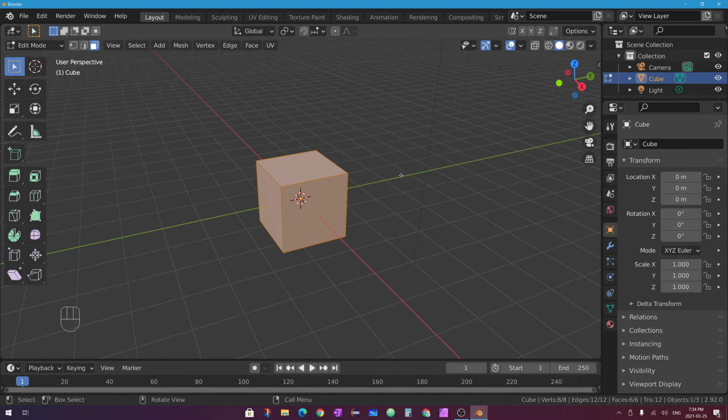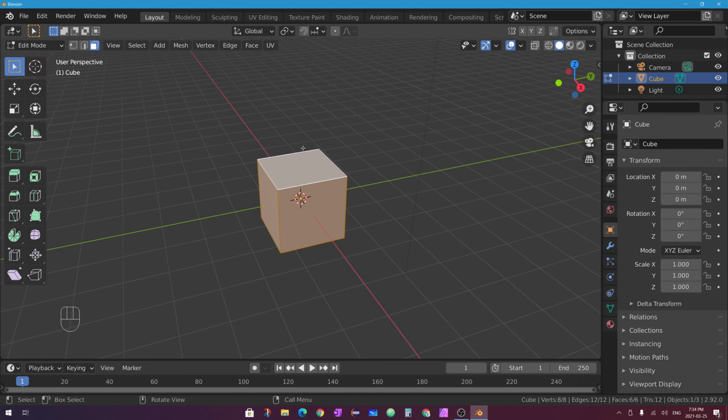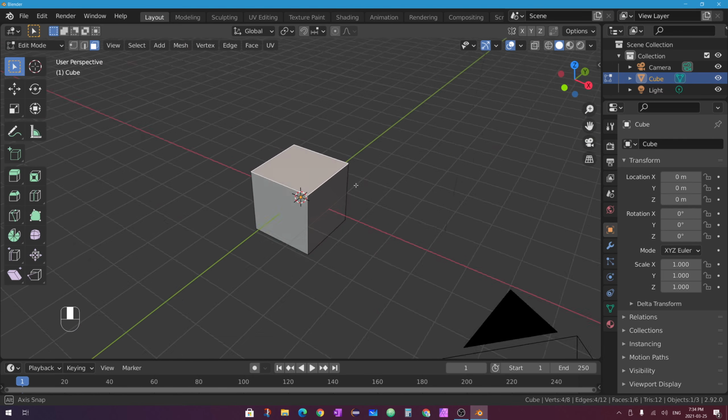There we go. Now in Blender, there are these versions of these common edit mode tools in our toolbar, but you should also know that there are legacy versions of these tools available to you using keyboard shortcuts. If I select a face on my 3D mesh, I'll select the top face here. By the way, please make sure that when you use the Extrude tool that you don't still have all of the faces on your cube selected. That would try to extrude them all outwards in some weird way. I'll select just one face to start with.